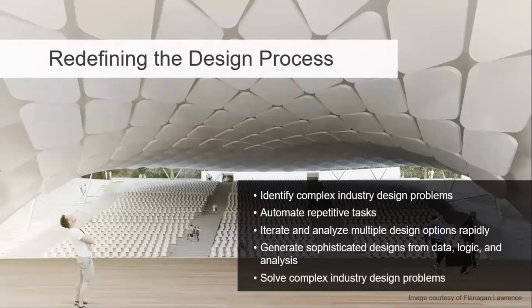Within Dynamo, there's a package called Project Fractal. In previous releases, Dynamo 2.2 and below, you had the option of using Project Fractal, but now it's included in Revit 2021 as a tab. There's a generative design tab. Users who are using the AEC collection are the ones who will be able to use this functionality for Revit. With this functionality, you're able to come up with different design options.